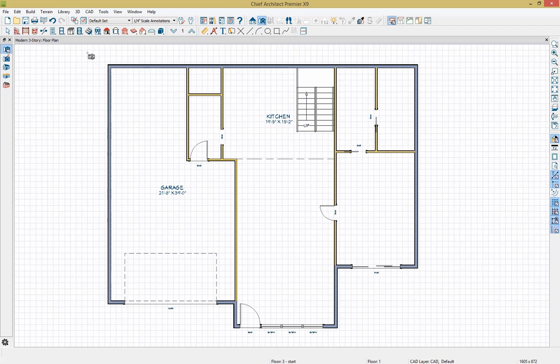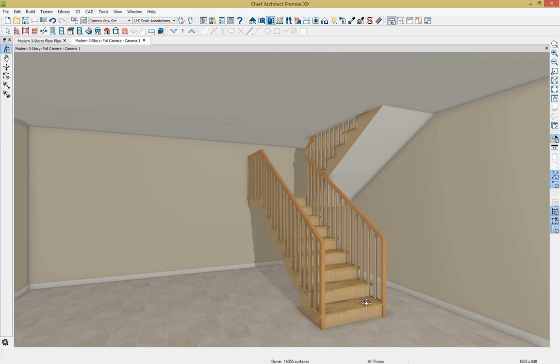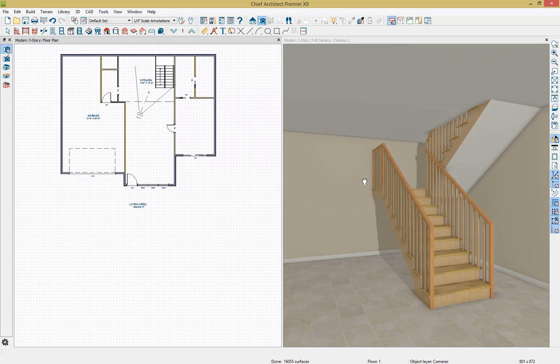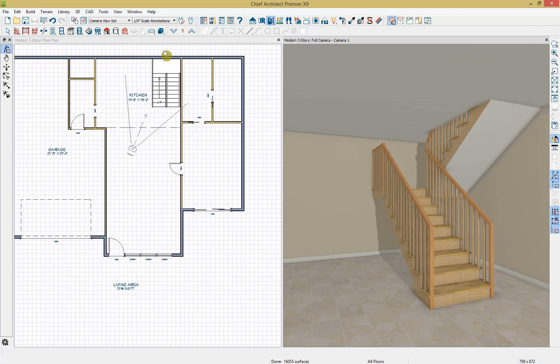And this time I'll be using our full camera. And that full camera is nice because we're going to stand in our room. I'll click where I'm standing and drag to my focus. So that'll bring us right into our space. And I'm going to tile vertically again, and we're going to drop in some walls underneath our stairs here.